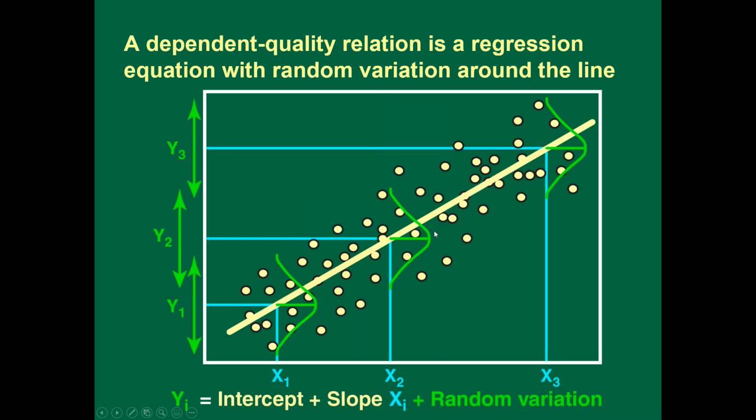So we get that random variation around the line. We use this kind of semi-deterministic method. From a sediment concentration, you get the line, and then the stochastic part adds noise or cloudiness around the line, so that the values that you generate will be this point cloud. They won't be right on the line.